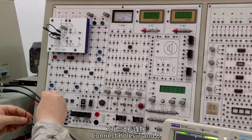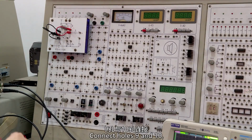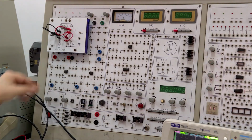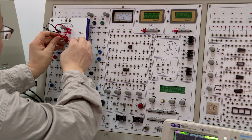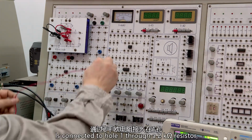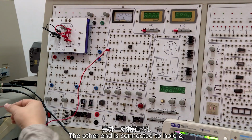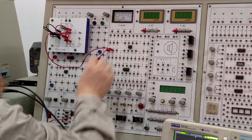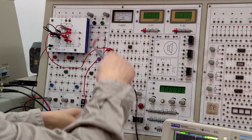Connect holes 7 and 8. Connect holes 9 and 10. Connect holes 10 and 11. One end of the signal generator output is connected to hole 1 through a 2K resistor. The other end is connected to hole 2. And connect the oscilloscope.